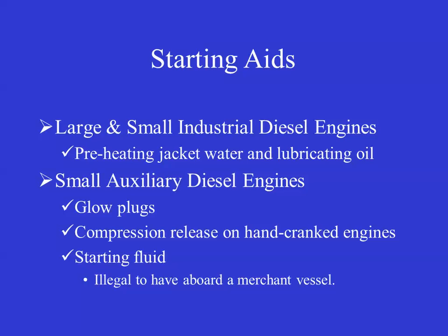It works quite well. What ether does is you take your air cleaner off and you spray a small amount of starting fluid into the engine. Crank it over when the engine starts. Then it's just that initial burn. Then you'll get enough heat that the engine will continue to run.